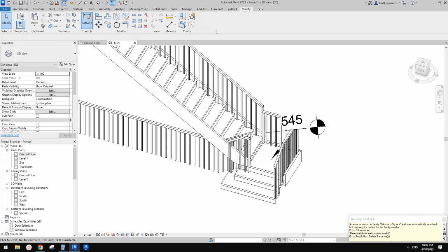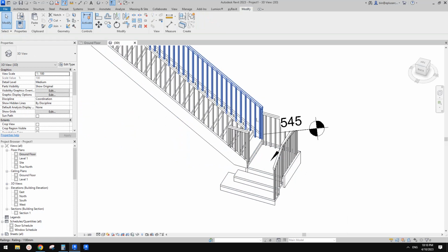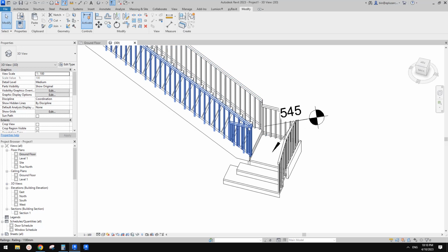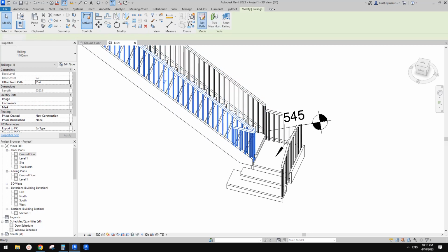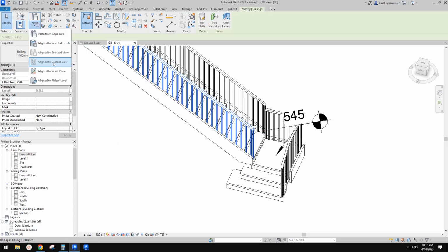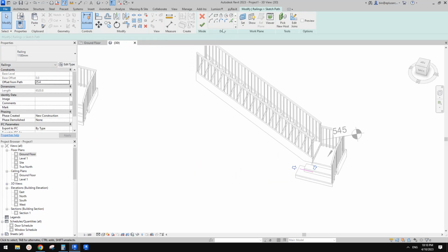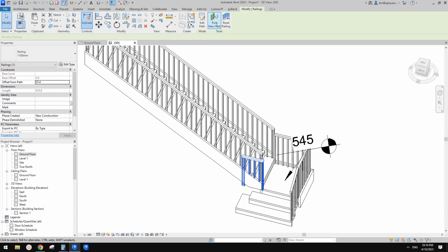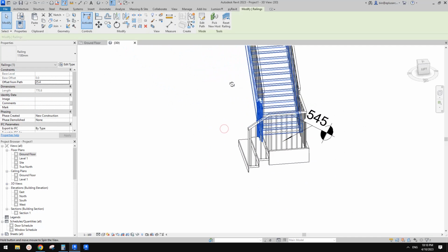It's either this one or this one. So it looks like we have to do 2. I'll just Control C, edit path, delete this bit, finish, and paste in the same place, edit path, delete the other part, finish, and then attach a new host to this. So this is how we can do it.